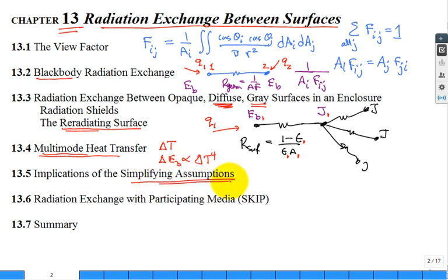All right, number of assumptions. One of the biggest is that you have to be careful anytime you're dealing with solar. A lot of times they'll give you alpha_S for a surface. What is alpha? Absorptivity. It's the solar absorptivity for that surface. And then somebody can say that surface has an emissivity, and that emissivity from Kirchhoff's law is equal to the absorptivity.